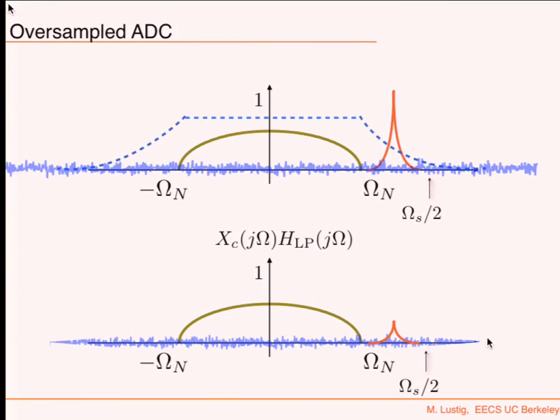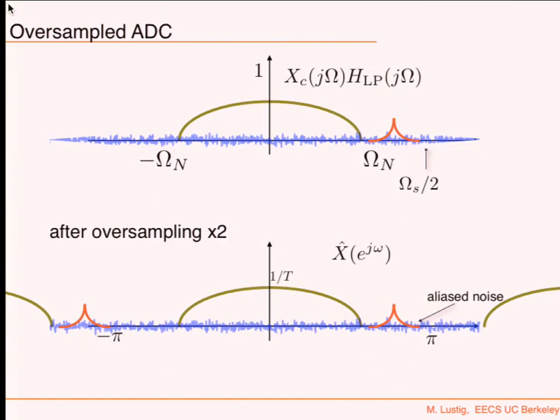Well, whatever's outside the bandwidth is definitely going to alias, right? So this noise is going to alias to here, right? Is it going to alias onto my signal? No. Right? It's not going to alias. And this is the whole idea. Okay? So after I sample, you see the noise is a little bit more pointy, meaning that it's decaying. Now this part aliases over here, and so I get this. Okay? So now the interfering signal is not overlaid on top of my signal. Okay? The noise outside of my spectrum also is not overlaid on top of my signal.